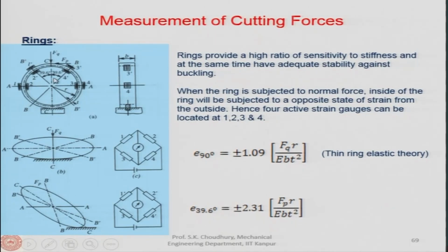This is not for all structures, this is particularly for the ring type structure that we are talking about, and ring type structures go through photoelastic studies to find out what are the nodes where the maximum strain can occur. This is for the purpose of fixing or putting the sensor in those positions.